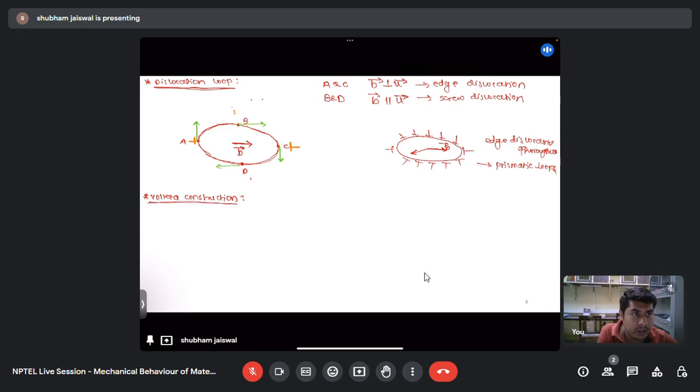We assume one hollow cylinder, and we cut it from one side, and then we translated it in the x, y, and z direction, and then we studied which translation in x, y, z gives which types of dislocation. Also, we have seen the angle. If we open that cylinder by some angle, some angular opening will be there, and that is nothing but a disclination.